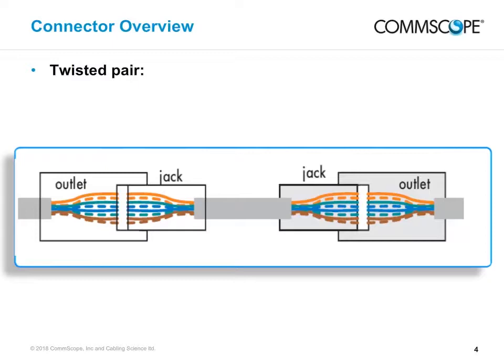Another point to remember is that while twisted pair connectors are physically interchangeable, one manufacturer's RJ45 style jack fits into another's faceplate, they do vary in termination techniques. The manufacturer's documentation will give the details of this. Twisted pair wiring is designed so that the same wires continuously connect from one end of the system to the other. That is, green to green, orange to orange, and so on, as shown here. In this respect, it is just like electrical wiring. This differs for fiber optic circuits.